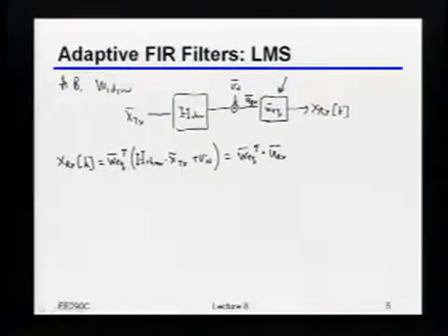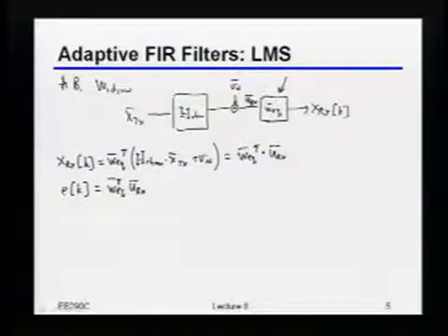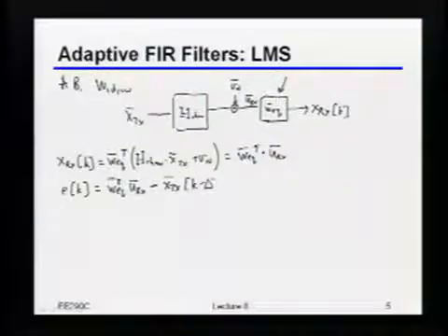But basically, if I wanted to figure out some sort of error signal at this particular sample, that error signal is just essentially after the equalizer, that's just a reminder, that's just u_rx. My error signal is just that, minus whatever I happen to transmit at some time, and actually this isn't a vector, this is now a scalar, at some time delta samples ago. Because assuming that there's some delay in this channel, you just want to handle whatever that delay is. So that would be my error.